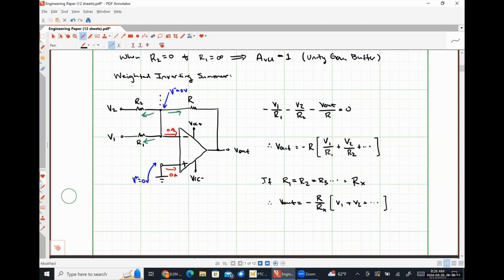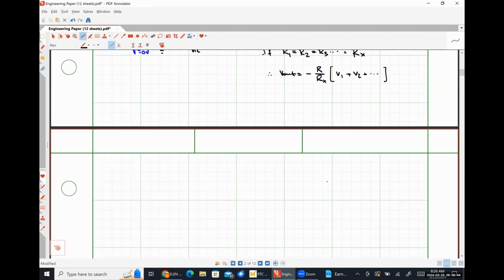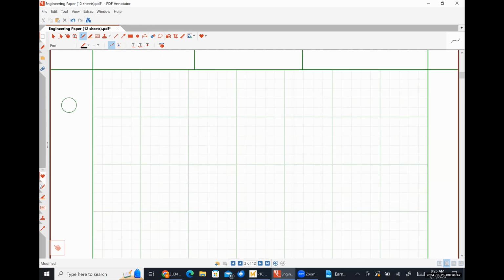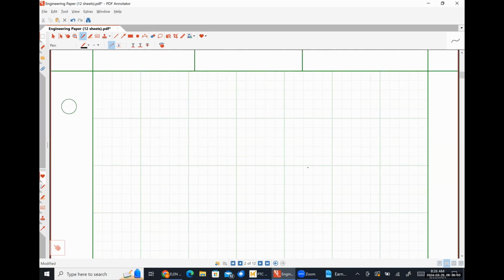You just take the output of your input sensors, which are just strain gauges for measuring weight. Their output voltage changes depending on how much they deform, and then you add those results together and it tells you, oh, this is how much you weigh. And the conversion between the output of the sensors and a proper weight is handled just by those resistor values. So we have done the mathematical operation of addition. So now let's do the mathematical operation of subtraction.